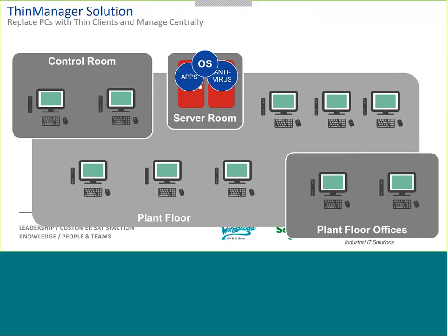What we don't show there is potentially in that control room in the top left-hand corner, that might be a single operator. So if we wanted to, we could consolidate that even further and have a single thin client between those two displays, and maybe even a single keyboard and mouse, so that operator can drive two displays from a single physical interface. So we've now removed all of the operating systems, all of the applications and antivirus from those physical machines and put them onto the terminal servers in that server room.